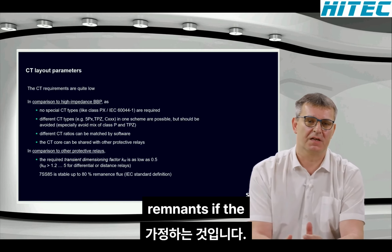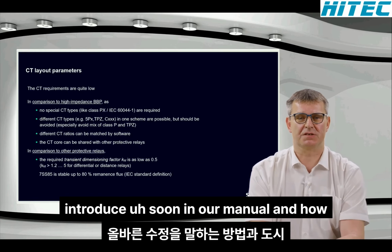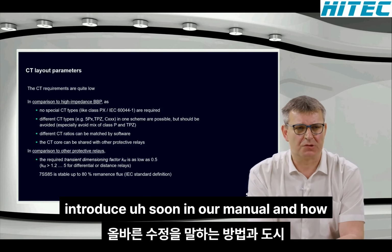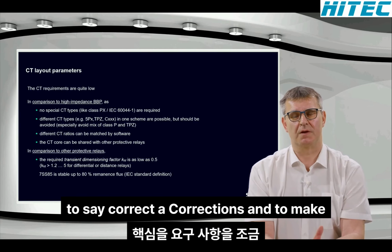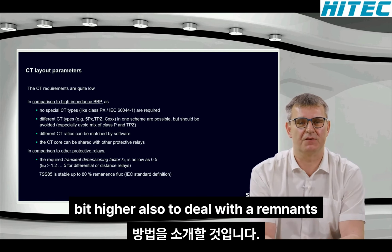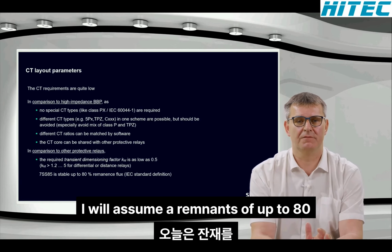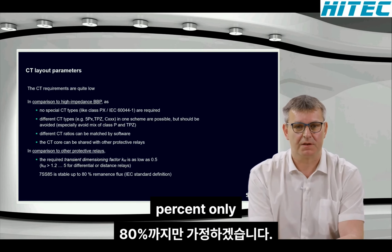If the remanence will be higher, we will soon introduce in our manual corrections to make the CT core requirement a little bit higher, to also deal with a remanence of more than 80%. But for today, I will assume a remanence of up to 80% only.